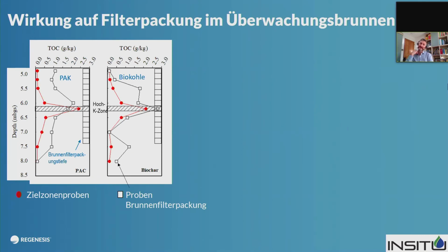Here we're looking at the filter pack of the well itself. The reason we're doing this is there was a study in the States where powdered activated carbon had been used on petrol filling stations, and those petrol filling stations were found to have great results. But what had happened is the powdered activated carbon had fractured through the formation, filled up the packing of the wells themselves, and turned the wells into filters. So the wells gave you great results, but the subsurface had not been treated.